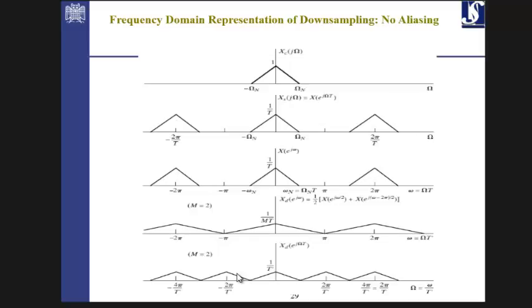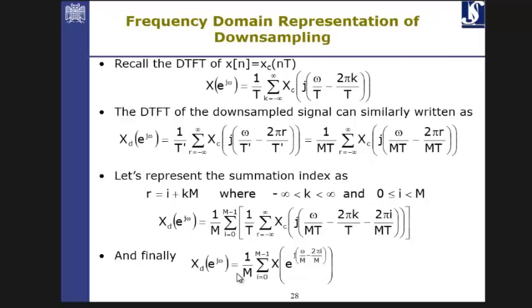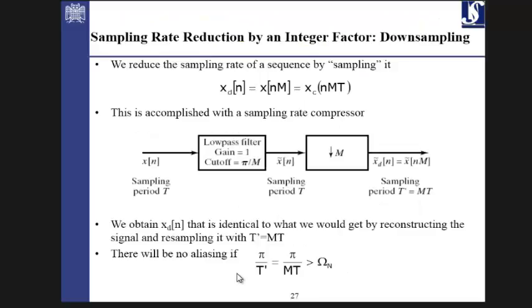You cannot just wildly take the M, something really large, because it definitely creates some kind of overlapping and you will lose information. So the point is that what happens for the downsampling is like that, but again, to avoid this kind of overlapping of the frequency patterns, what you can do is the same as an anti-aliasing filter. You can just use the low-pass filter in the beginning. That's why in the downsampler, they use a low-pass filter in the beginning.